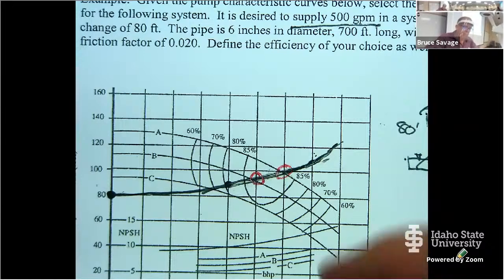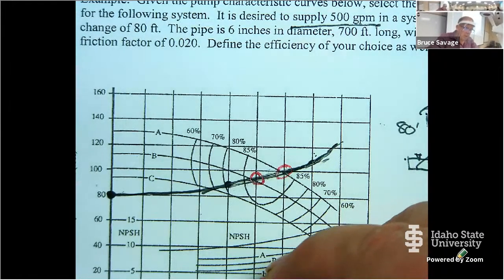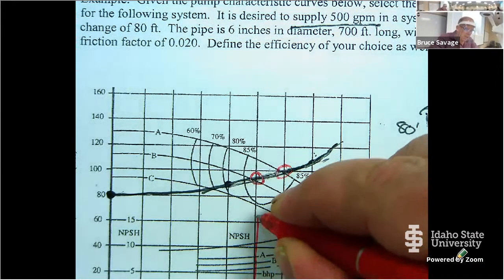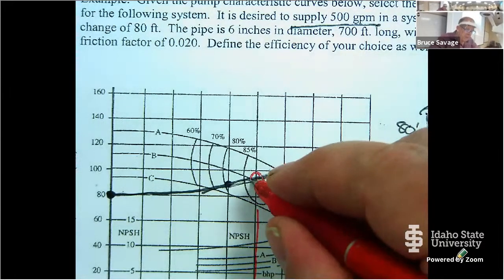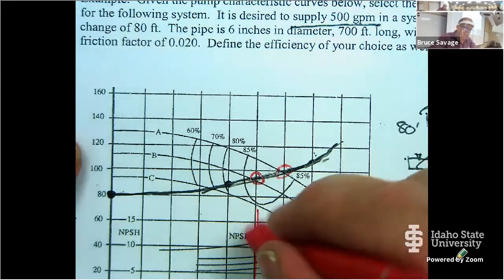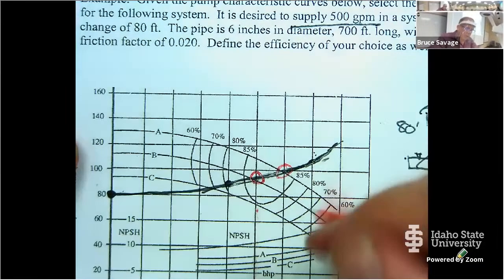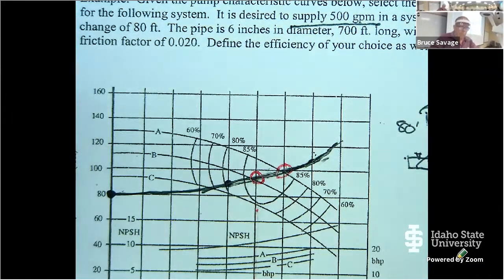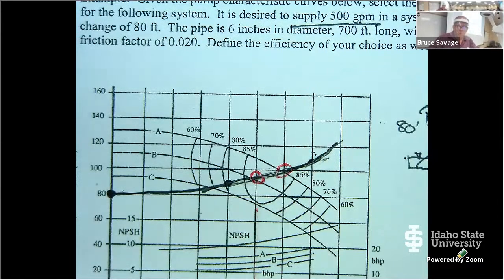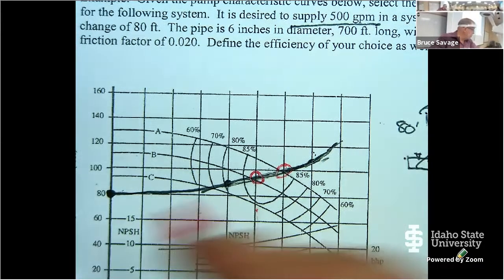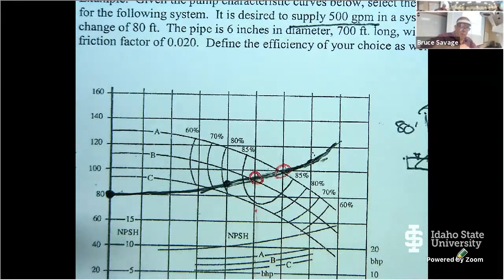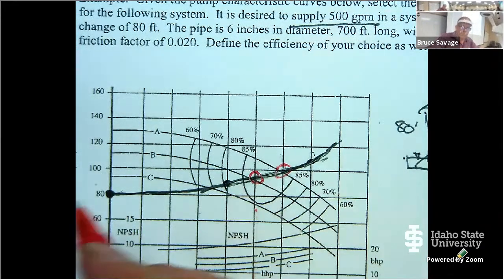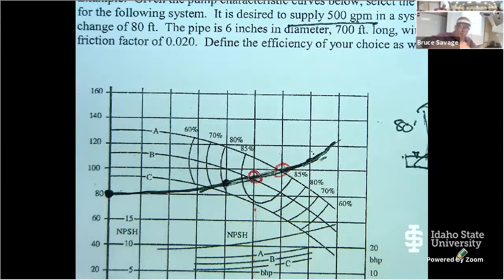So if I choose impeller B, now, actually, well, I gotta be careful. This is actually really good. If I have this drawn very carefully, and a regular pump curve would be a little bigger, I'd probably use a French curve on this, or a flexible ruler, if you've ever seen those, or I would plug it into the computer program.